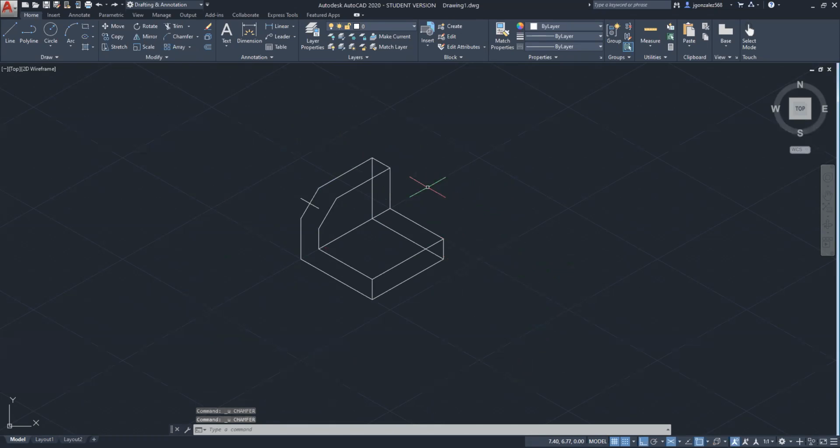And do that one more time. So choose the chamfer, select distance, 0.5, enter, 0.5, enter. Top edge, redo that top edge again. Click down here, and then again over here, so repeat it 4 times. After that, just delete this excess nonsense.